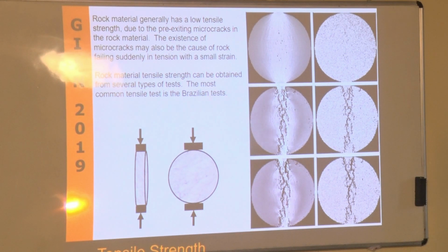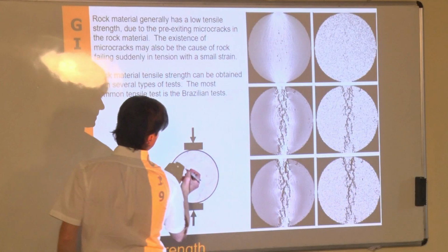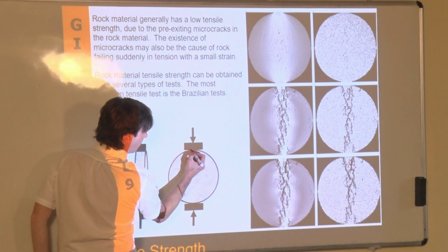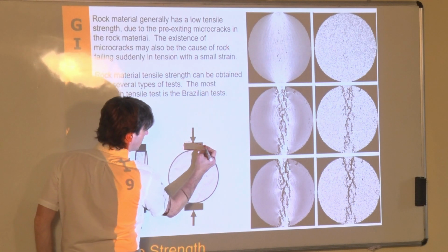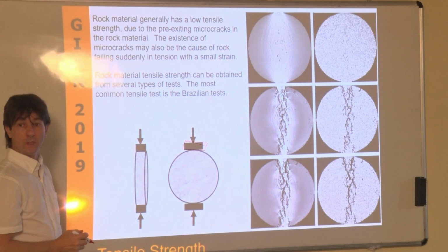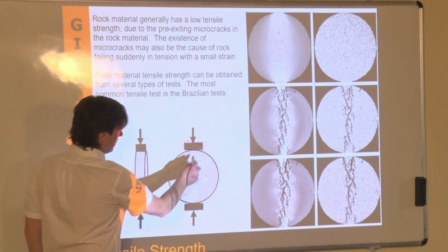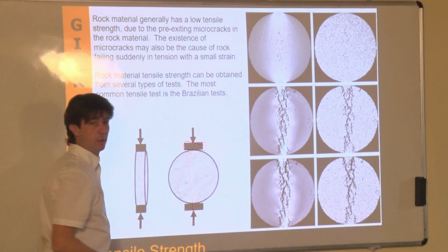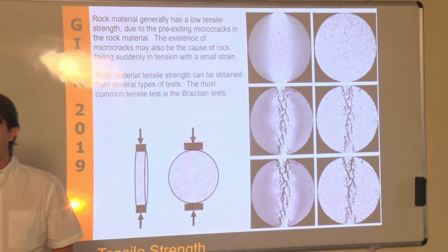One of the big problems that we recently found, just to share, is that instead of having a platen that way, you have a platen slightly oblique. What it means is that your loading axes are not really meeting at the center.